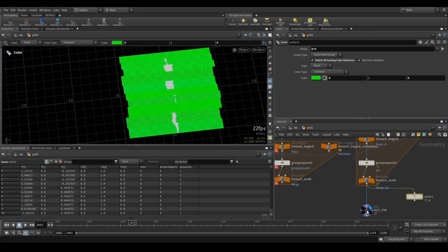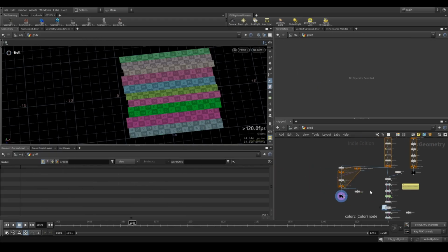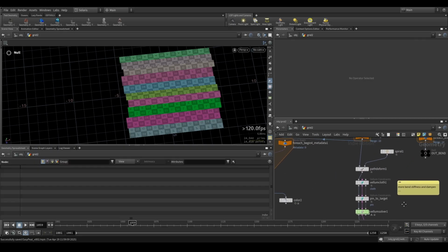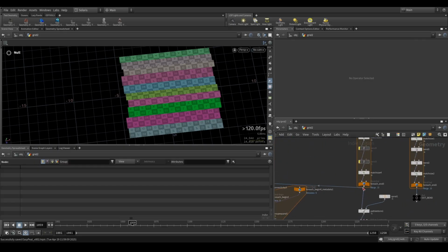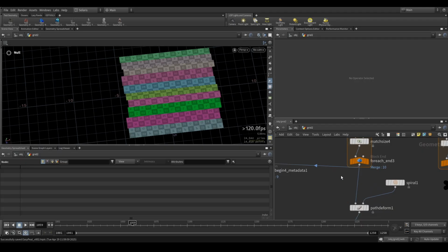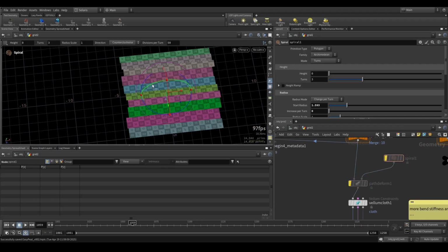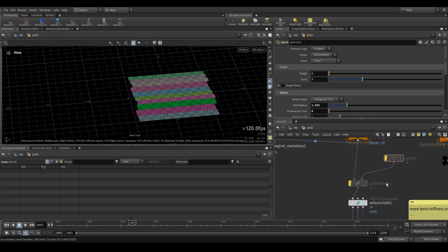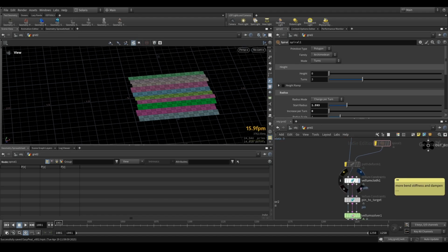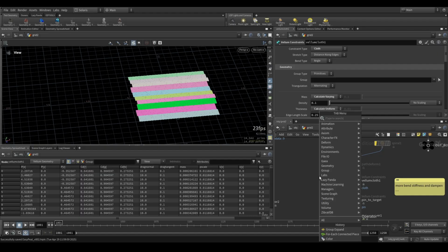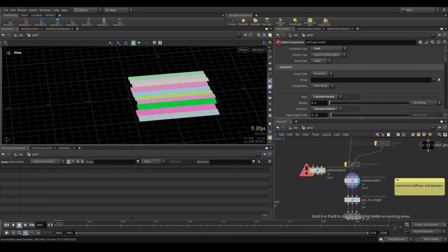And again, from there we do an out pin. Let me remove this again. And this is what we're going to use in the Vellum solver as well. So to use it in the Vellum solver, let me actually not do the spiral thingy for now, so we keep it flat, so it's a bit easier to understand. And we just need to create a Vellum cloth. So you just put down literally a standard Vellum cloth. You can type Vellum configure cloth.